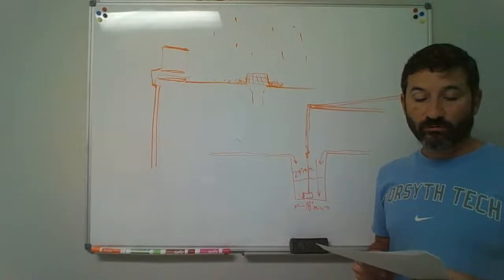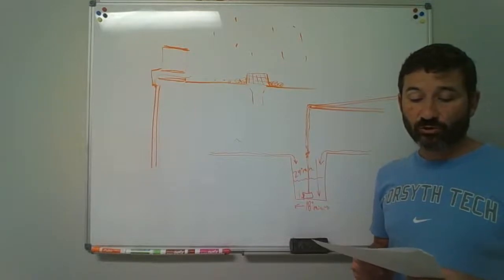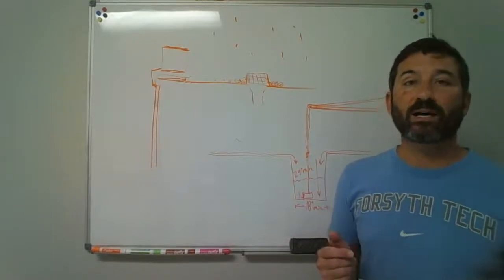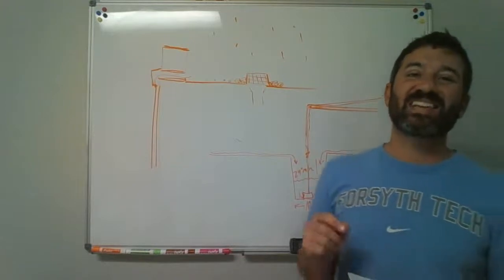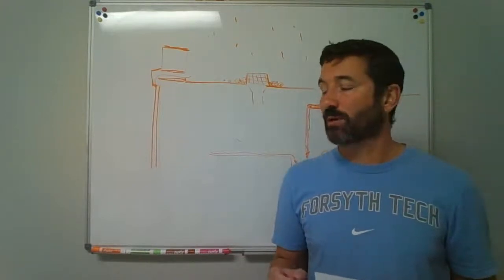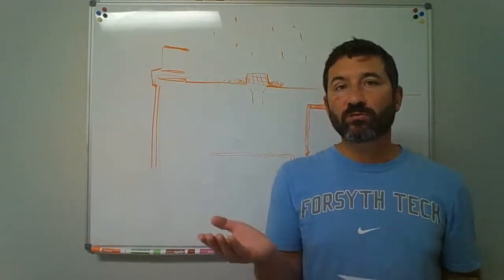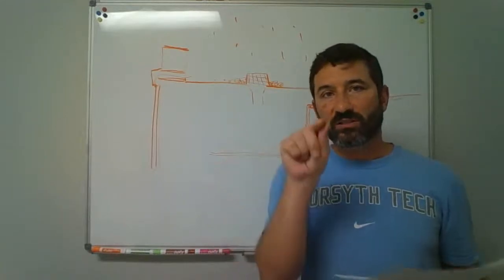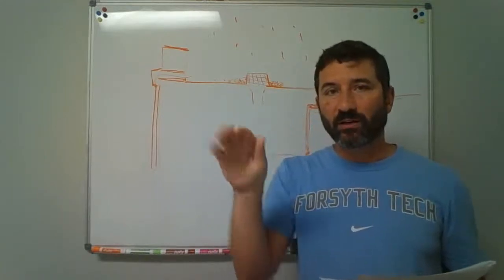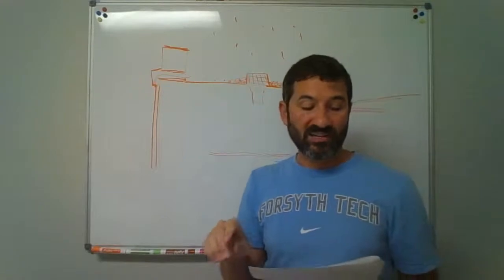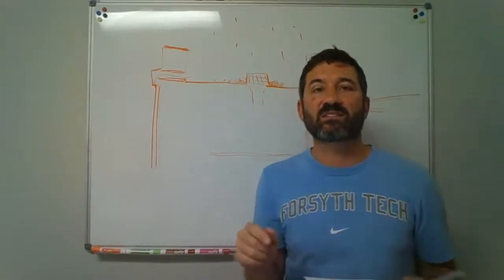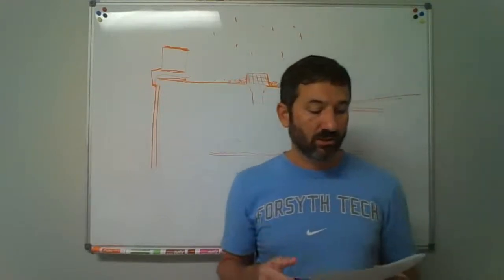Question 8, true or false? PVC can be used for subsoil drain pipe. So you need to flip over to the chart. It says subsoil drain pipe above it. Look down through the options and see, is PVC listed? If it is, then yes, you can use it.